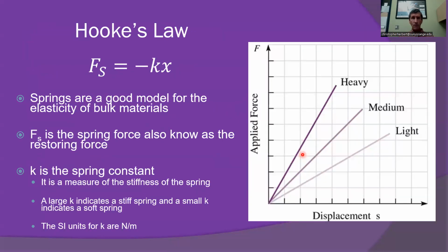Now, again, Hooke's law, which is basically relating the force to the amount of stretch of a spring, the amount of displacement of a spring, is a good way to model many of these systems. We basically say that the applied force that we place on a spring is equal and opposite to the spring force. Actually, the applied force is proportional to the displacement, equal to kx. The spring's response, the reaction to this, of course, will be negative kx.